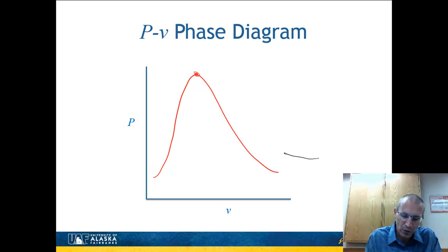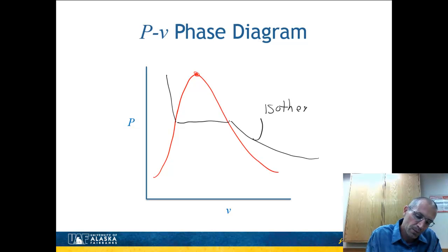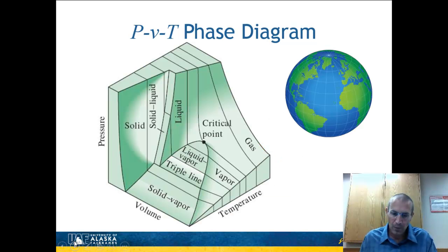It begins over here in the superheated region. It goes straight across the mixture region and then up very steeply. So this is an isotherm. And again, we see any two variables define the system. Here we're using P and V, and we can go ahead and find any other state out here. Okay, so there's a review of two-dimensional phase diagrams.